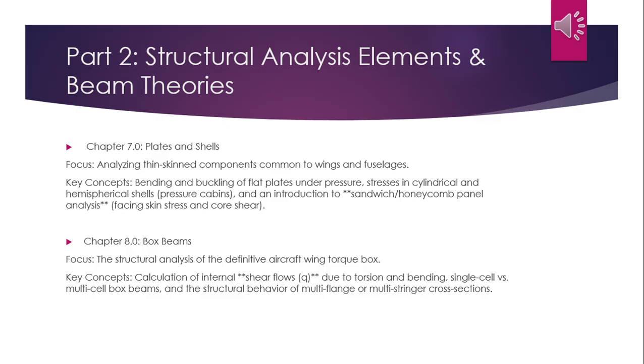Chapter 8 is box beams. It focuses on the structural analysis of the definitive aircraft wing torque box. The key concepts are calculation of the internal shear flows due to torsion and bending, single-cell vs multi-cell box beams, and the structural behavior of multi-flange and multi-stringer cross sections.